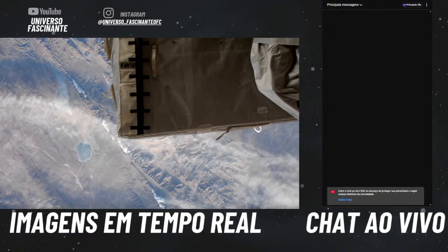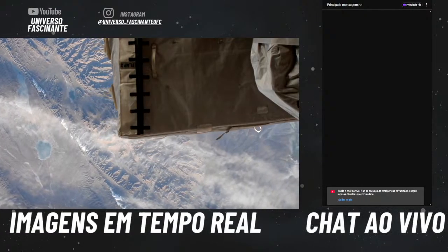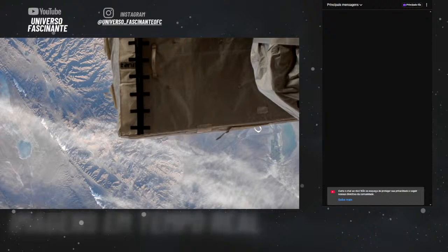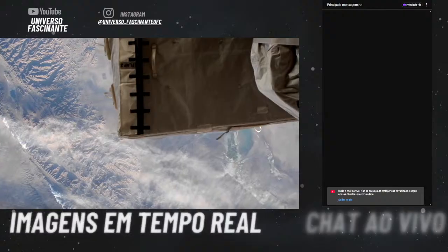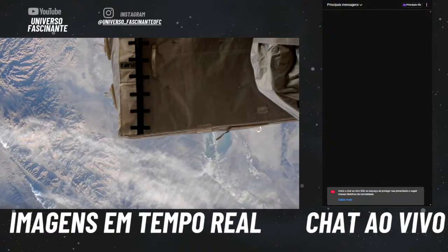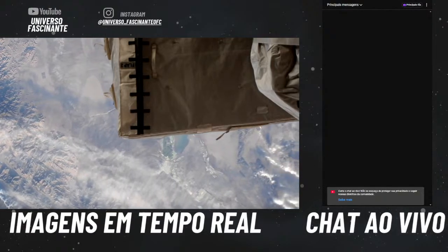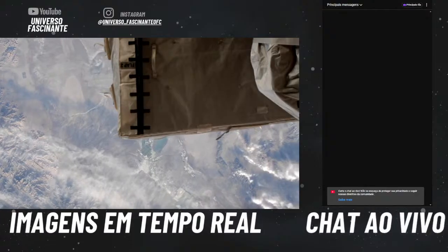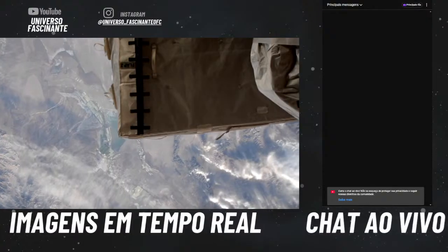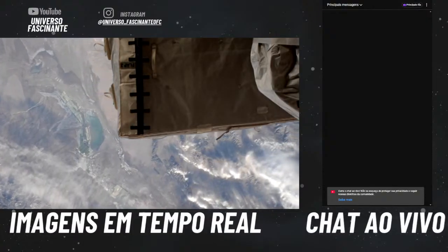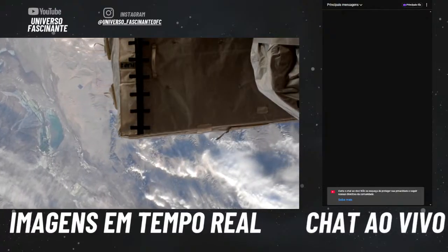Just to reset some of the upcoming events, the undocking command is scheduled just over 3 minutes from now at 7:40 p.m. Central Time. 90 seconds later, physical separation. 3 minutes after physical separation is the first of 2 separation burns of the Soyuz thrusters. This will be an 8-second burn to increase its departure rate by 0.53 meters per second. The second separation burn occurs about 1 minute and 20 seconds after that, a 15-second burn to further increase the opening rate by 1.61 meters per second.